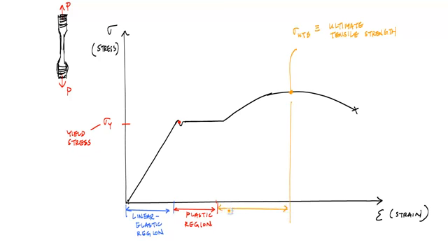And if you talk to a material scientist, they'll say that it's where you've got way too many dislocations and there's no more room left for dislocations, and so the material is able to take on more load and reach this ultimate tensile strength. Another way to look at it is kind of like all the grains and everything lined up just right as you were in this plastic region, and then all of a sudden it was all lined up and just holding down as much as it could, and now the load starts increasing here.